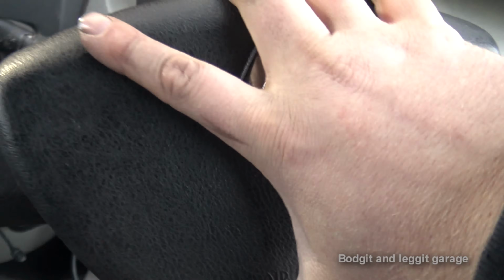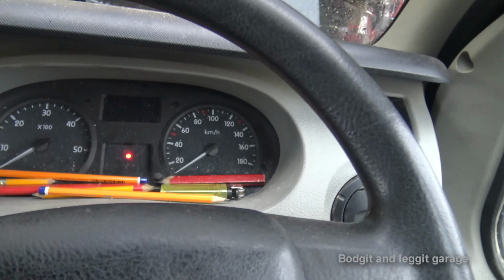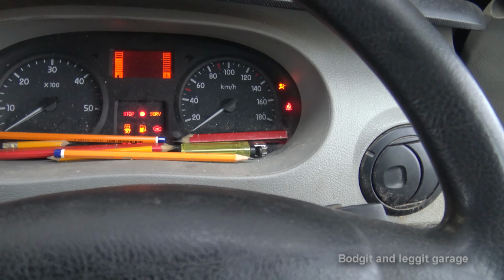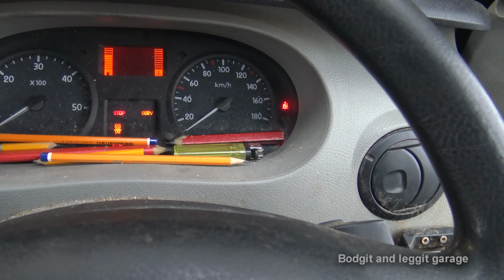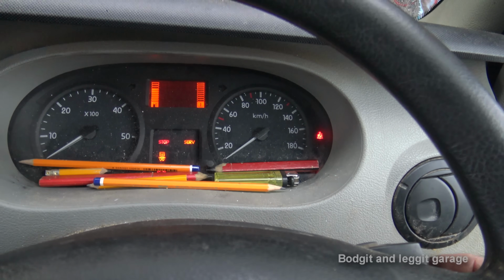Right, the airbag isn't properly in, it's just clipped. So let's turn the ignition on. First, let's just turn it on. Oh, the steering lock's up. There we go. Yeah, airbag light goes off. Let's just make sure it doesn't come back on just before we start it, which it doesn't.